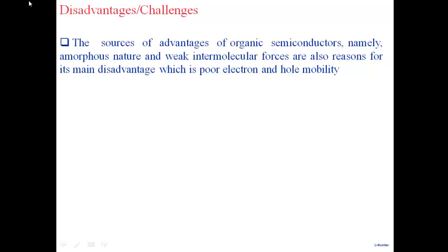Now, you know that displays are like a matrix. And some of you know from your early CRT, you go and display the first row and then the second row and the third row and all that, right? And then you display the whole frame. And after you display a whole frame, then you go back to the first row. Now, what is the frame rate that you're familiar with? 24, or 50 hertz or 100 hertz, something like that. So once you switch an LED on, after how much time do you have to come back and switch it off? It's like 100 hertz. You don't require very high speeds here, right?